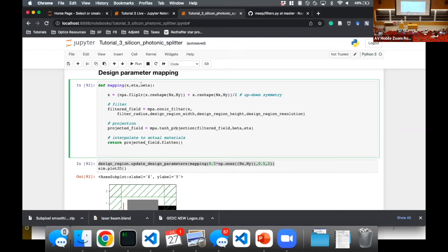And the downside with the step function, of course, is it's no longer differentiable and there's all sorts of problems, right? So the challenge with density-based topology optimization is slowly ramping up this binarization constant in such a way that the design remains differentiable, but it's still binary at the end of the day. Okay, so there's a lot of art that gets mixed into this, and we're going to talk about that once we start getting a little bit more hands-on.